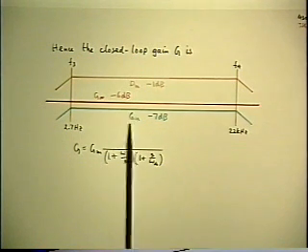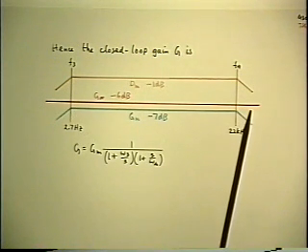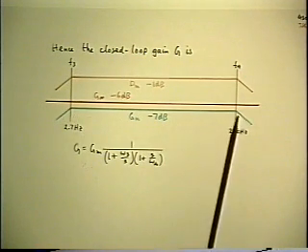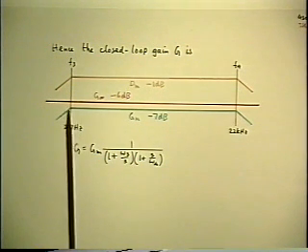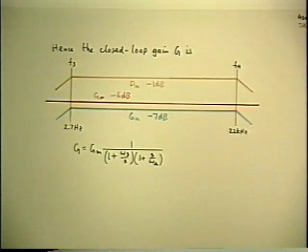So the conclusion is the actual amplifier will give you a gain which is pretty close to the ideal value, the specification, over the frequency range, 2.7 hertz to 22 kilohertz, and beyond those limits, the actual gain will drop off, will deviate significantly from the G infinity.